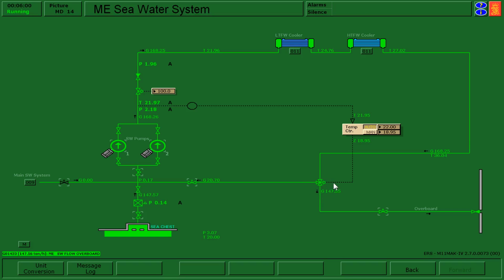What this device is down here is it's a valve, and I have two potential exits from the valve. I have an exit going this way, which would be the hot water that could go back into the system and recirculate, or I have a pathway that I can reject overboard. This system, what we're doing is we're running it at about 22 degrees. And since I'm bringing in seawater at 20 degrees, I got to recirculate through a bit of warm water.